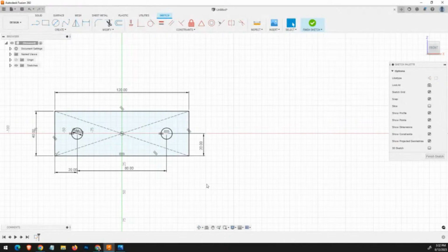Okay, so this is just the first part. I hope we can finish this one assembly. So these are some techniques, tips and techniques to make it easier to do the project. We really need to identify this using the constraints. We master the constraints and where they are used, so that when we see the project, we can say: horizontal, vertical can be used here. Coincident. Tangent. Equal. We are faster when we use equal. Okay, John Vincent.